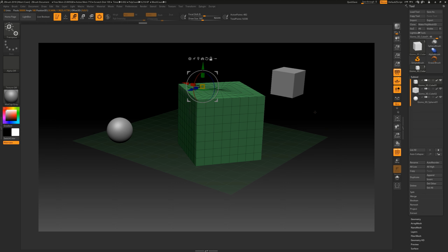To reset the rotation of the Gizmo 3D tool, first unlock the lock mechanism and then click on the Reset Orientation button option. Instead, we can hold down the Alt key while the lock symbol is engaged and then click the same button.